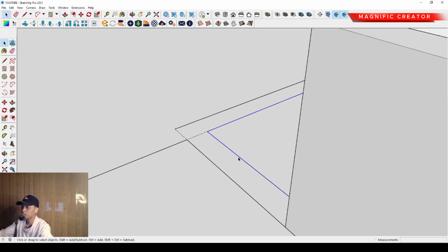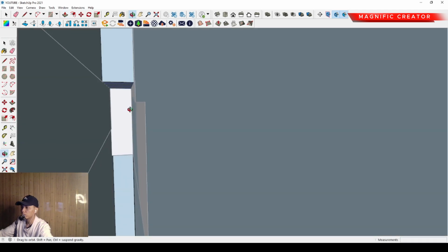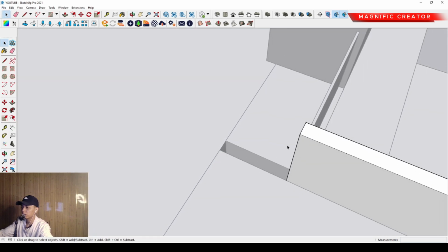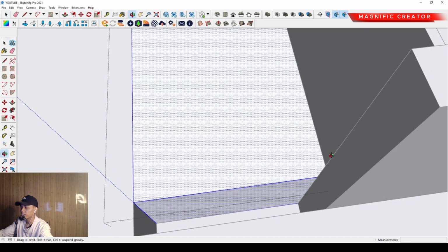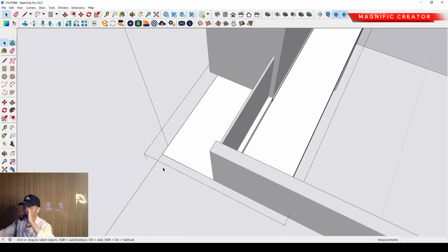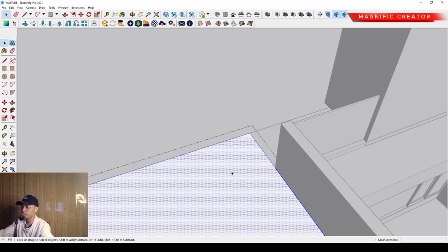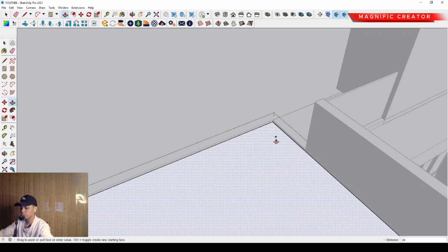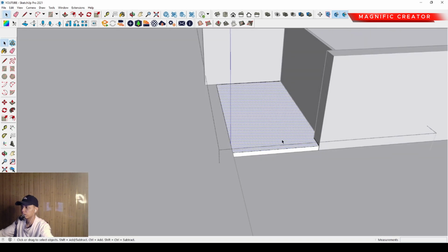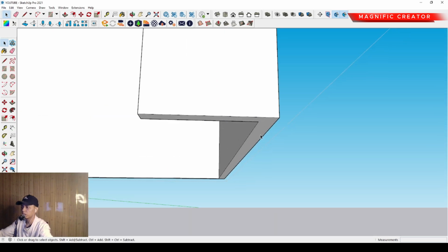And also we can push the wall till this position only, so we can complete this balcony position. We can push it until this position, so we can set the difference level between the first floor and the semi-outdoor floor with around 50 mm for the distinction of elevation. Then so we can complete it all.